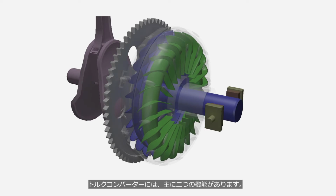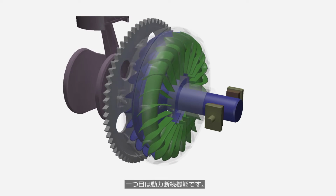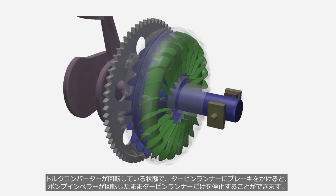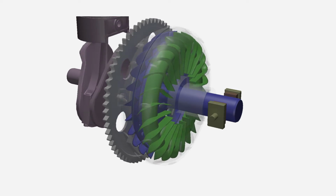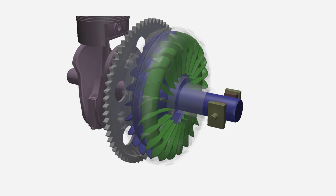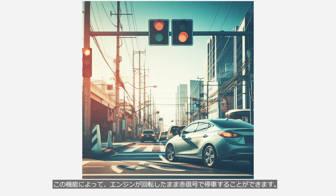A torque converter primarily serves two functions. One of them is the power flow cutoff function. When the torque converter is rotating, applying brakes to the turbine runner allows it to stop the turbine runner, while the pump impeller continues rotating. This state is referred to as torque converter is slipping. This feature allows the engine to continue running while coming to a stop at a red traffic light.